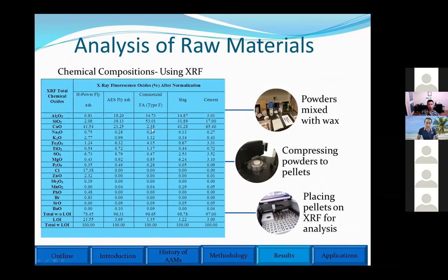As you can see here, we just have 2%, less than 5% calcium. It means that if I want to produce geopolymer concrete or alkali activated material out of type F fly ash, I have to add something like slag that has enough calcium. With a good amount of alumina and silica out of the fly ash, and enough calcium out of the slag, I can get good properties.